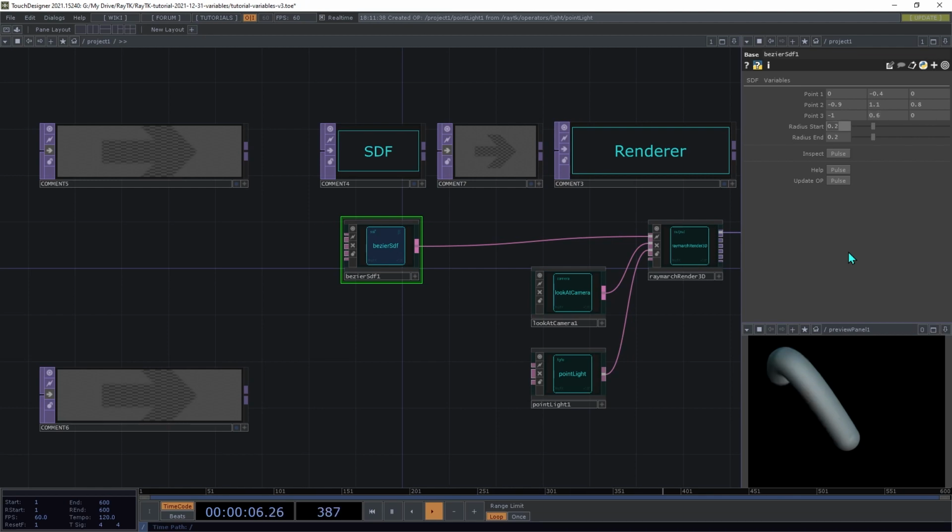Now we're going to be controlling this third point using a field, but moving it here will make it easier to see what's going on until we get to that point. So you may notice, if you try playing around with some of the positions here, that there can be combinations of positions that cause some rendering errors, so you'll need to keep an eye on that when you're deciding what points you want to use. That will typically manifest as either gaps in the surface or creases like that. So going back to our original shape.